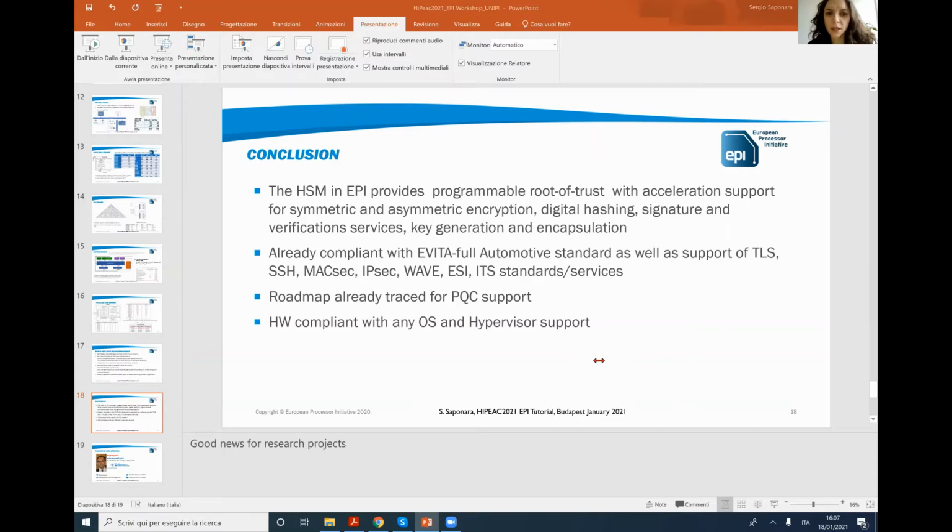Okay, the next one is: do the general purpose CPUs contain metric counters that can be analyzed by the secure tile to identify statistical deviations that might hint at an attack? Yes, for this part, as I said in the description of the feature, there are several resources that are implementing techniques to take care of side channel attacks, and indeed one of the goals of EPI2 will be, in the bring up, to measure this, since obviously we are making a design, we are synthesizing some feature. When we speak of side channel attack, so power attack, electromagnetic attack, they are really related to the hardware implementation.